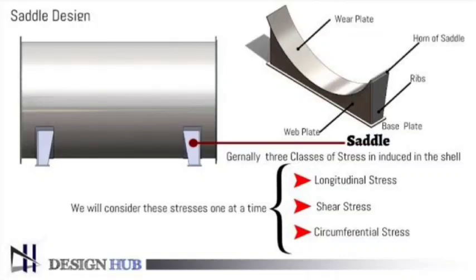Okay, as Himanshu told, we need to consider a wear plate larger than what is given in PVElite. Even if the standard says less, we have to go with the higher value that comes out of the calculation, and show it to the client if we get a value higher than what the standard shows. Yes, correct. And Abhishek, as Himanshu told, if you increase the length, meaning the width of that one, your problem gets solved. Yeah, it is resolved like that.